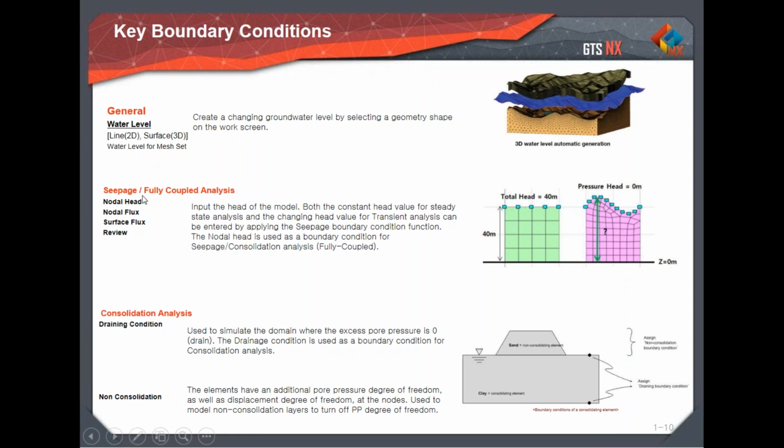But what we'll be seeing actually is that for the fully coupled, you can create these drainage conditions using seepage boundary conditions, where you can actually control and hence even create suction, like negative pore pressures, instead of only relying on a drainage condition that's general and setting it to 0. So consolidation in itself is a little more basic, if you will, or has a lot of assumptions that the fully coupled allows you to control or account for.